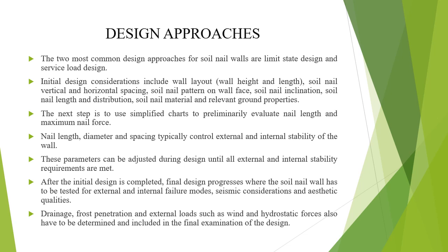Now, design approaches. The two most common design approaches for soil nail walls are limit state design and service load design. Initial design considerations include wall layout, wall height and length, soil nail vertical and horizontal spacing, soil nail pattern on wall face, soil nail inclination, soil nail length and distribution, soil nail material and relevant ground properties. The next step is to use simplified charts to preliminarily evaluate nail length and maximum nail force. Nail length, diameter and spacing typically control external and internal stability of the wall.